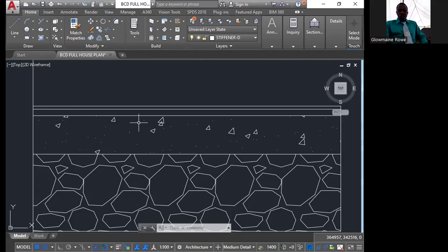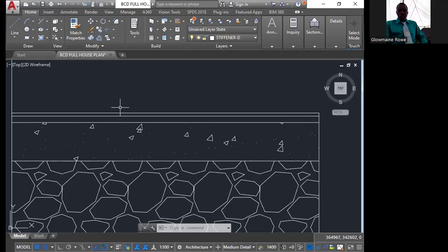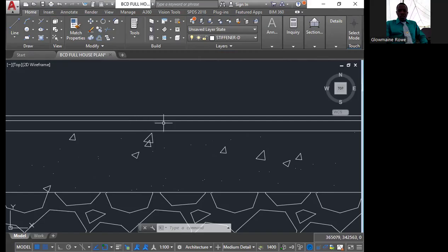All right, so now the layer above your concrete is called your floor screed. Anybody ever see persons laying tile before? They mix the cement and the sand, with no gravel in it. You have the trowel and then put it on the floor, then put the tile and set it. Anybody ever see that? Yes, so this is what they call the floor screed.